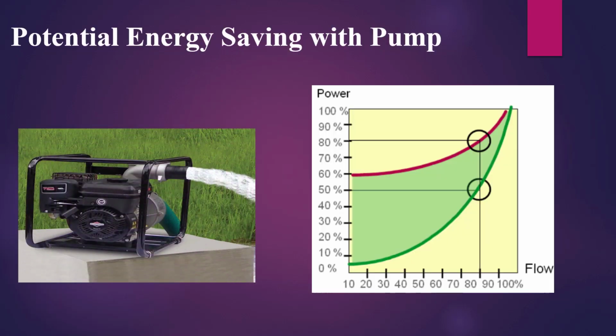How is energy wasted in water distribution? Let's look at an example. In a distribution system, water is moved by a pump. In this simplified irrigation installation, the pump is powered directly by an AC supply and always runs at full speed, whatever the demand. A valve opens and closes to vary the flow. Reducing the flow using a valve causes what are called load losses. As the valve slows the flow of water, a large part of the power is lost.